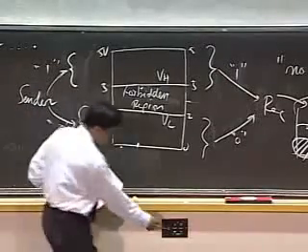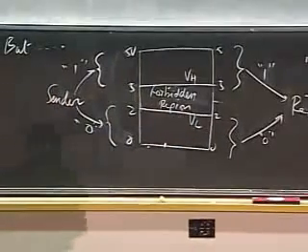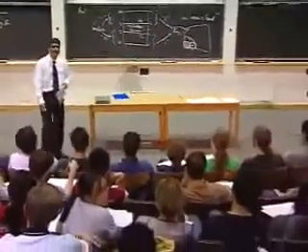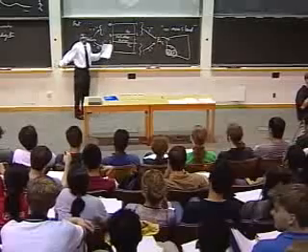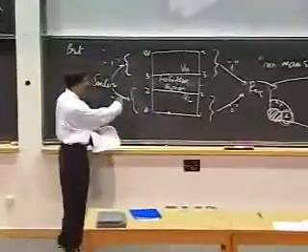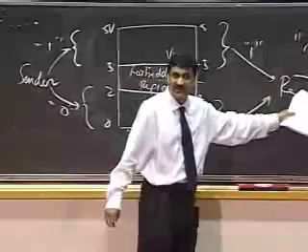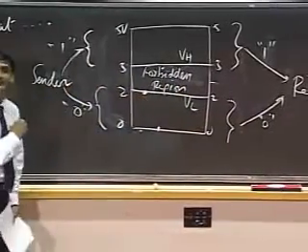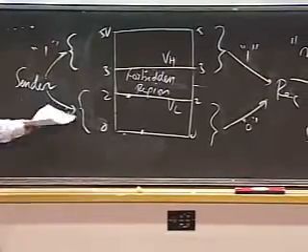So do you see what the problem is? Yes? If the sender sends 1.99 and noise pumps it into the forbidden region. Exactly. So the sender says, look, it's legitimate. I'm Intel, right? They've told me, stick to 0 and 2. And Intel parts will be sending values between 0 and 2. And Motorola parts, which are receivers, have to receive 0 and 2. But Intel can send a value of 2 volts. I mean, they can because it's 1.99 or 2. It's legal.